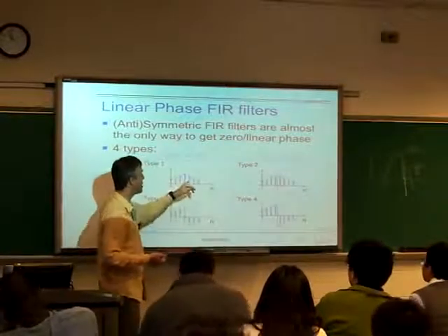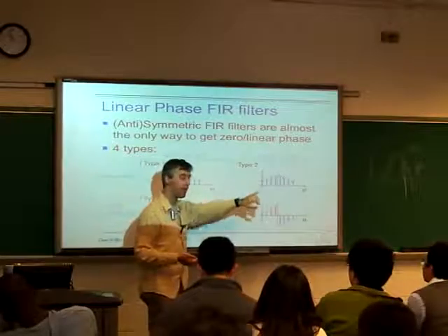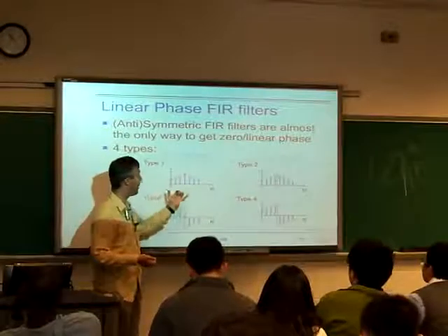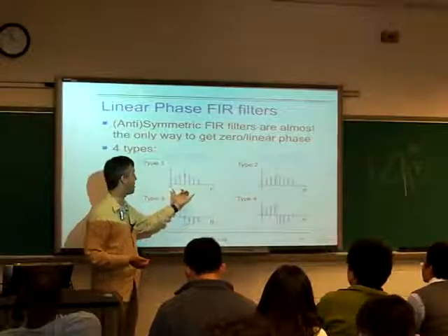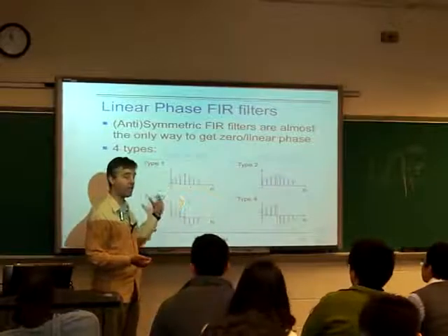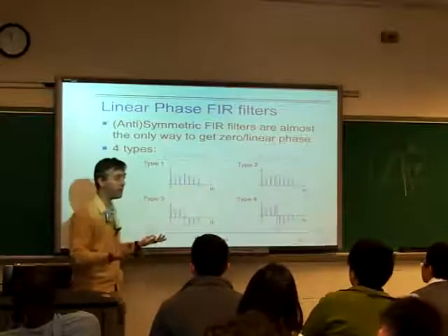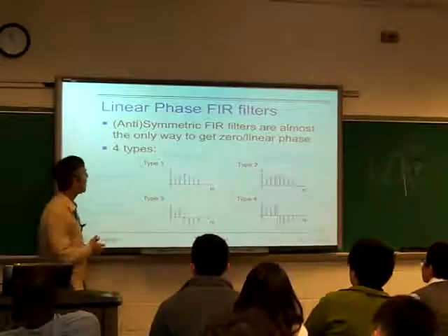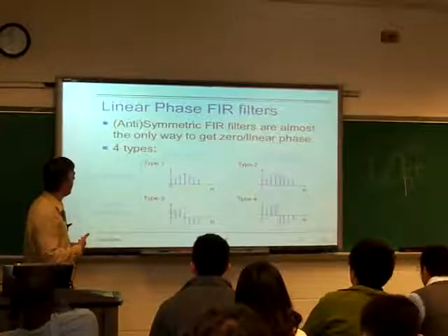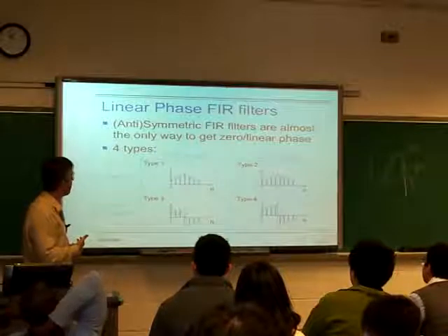So you could build impulse responses with arbitrary structure and arbitrary symmetry, and this idea of linear phase actually amounts to the same as having a time symmetry in the impulse response. And so you could build these, which you could never build with causal feedback systems with poles. So that's the general idea.